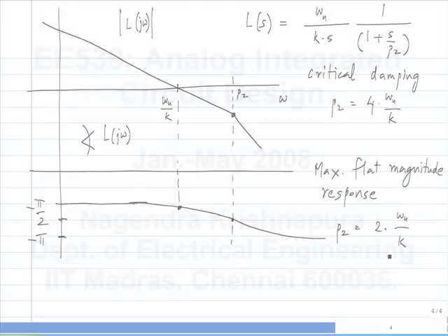Right? Now, you are supposed to make a negative feedback system, and the way the system is defined, if L is positive, it is negative feedback. So if L has a phase angle of pi, it is positive feedback. So phase margin is a measure of how far away it is from this positive feedback condition. So this phase, that is the phase at the unity loop gain frequency, away from 180 degrees, this is the phase margin.